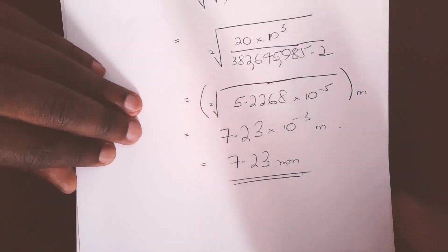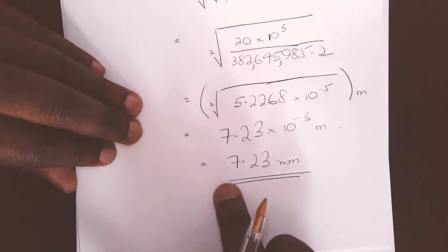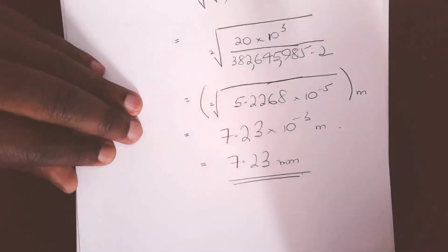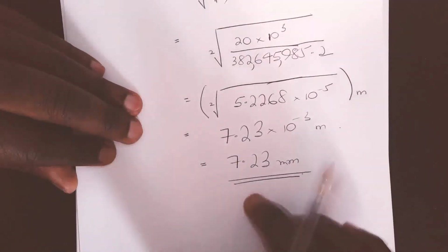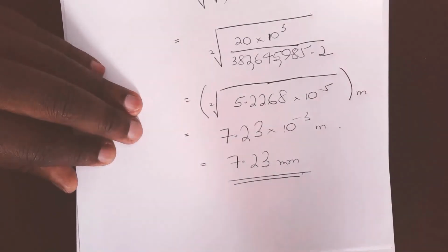Now, if we're going to make this bolt, we need to look for the nearest bolt size to this value. One thing I would recommend that you don't do is to round down the number. It's better to round up, to add a little bit of margin of safety from a design perspective, and you can also look at that from a cost perspective, but that's something we can talk about down the line.